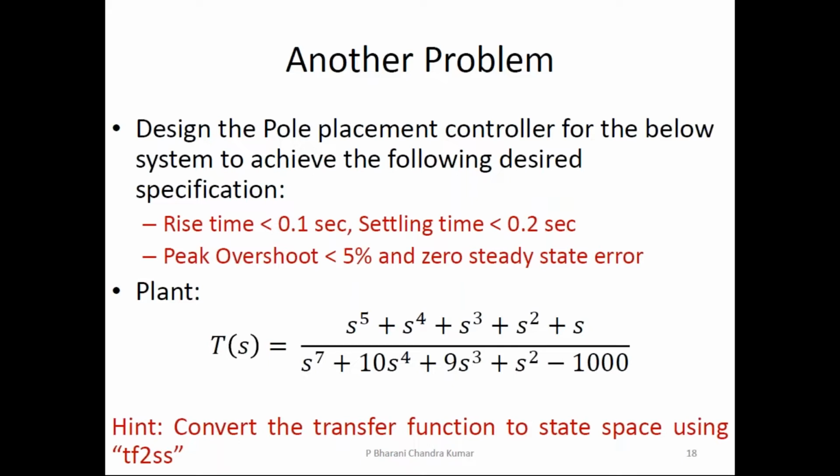If you want the speed in less than 1 second, the power electronic voltage controller should act fast enough to give the response very quickly. You control it using the gate circuit controller, the gate pulses. If you control the gate pulses accordingly, that controls the power electronic voltage controller, which gives the corresponding voltage to the plant, basically through PWM control techniques. That is how it happens.